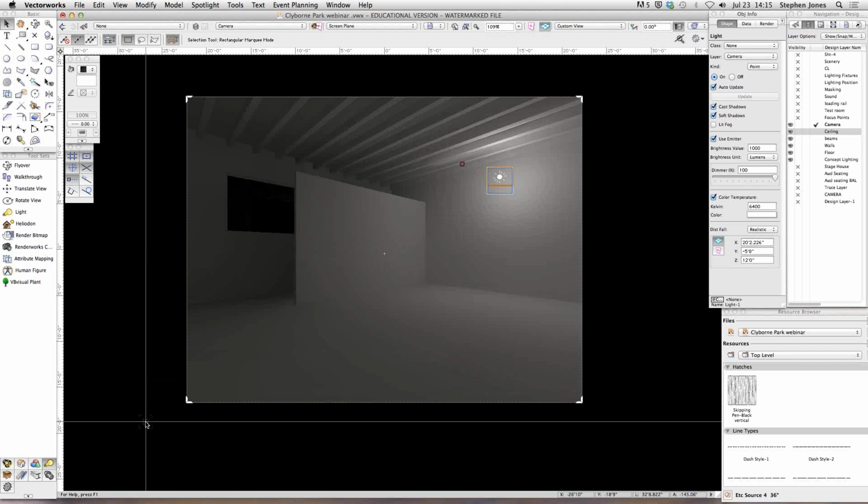The interior 4 bounce is definitely the highest quality interior option that I've, to my knowledge. Something to note though, each of these options increases the rendering quality, but it also really taxes your computer or slows down your computer's performance, and it's very, very noticeable if you have an older computer. It can take a long time to render something if you have multiple lighting sources and you're using the interior 4 bounce. So just a word of caution there.